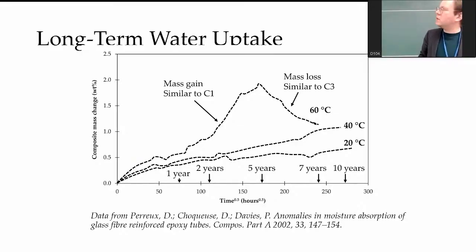And what happens is that the whole composite keeps degrading, and there are pores, like voids, becoming inside of it. And these pores are being filled with water with time. So it's not like it's chemically or physically bound, but it's just filling the voids. And therefore, we have this increase in volume. However, when this volume starts to connect together, they make a channel.